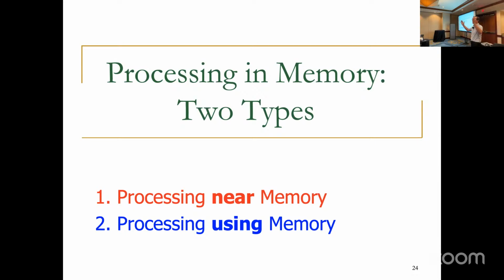Basically, you have memory and you have logic. You design them completely separately, but then logic may get closer and closer to memory arrays. It could be inside the DRAM chip, but logic and memory are still separate, and they're separately designed. Whereas processing using memory is fundamentally different from today's systems, where you don't have logic. You forget about logic for some time. You take the memory circuitry and you understand, exploit, or enable better ways of using operational properties of these memory circuitry to do analog computation. So you exploit the memory circuitry. There's no different way of designing logic.